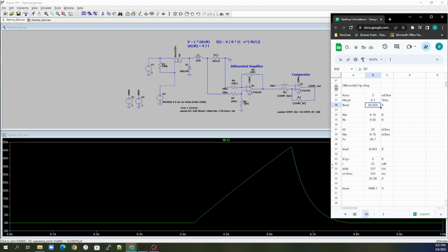I chose 3 volts because, you can choose anything that you want for the V reference, but if you remember from the data sheet, this LTC6244 has a max VN on the input pins of 3.5 volts. So I was keeping my reference under that, so I have some headroom because I do want to add in some hysteresis. So now we have to think about that right now our differential amplifier is set up for 4 volts out, but that is no good for this comparator, since we know that the comparator itself has to have an input voltage on the pins of less than 3.5 volts.